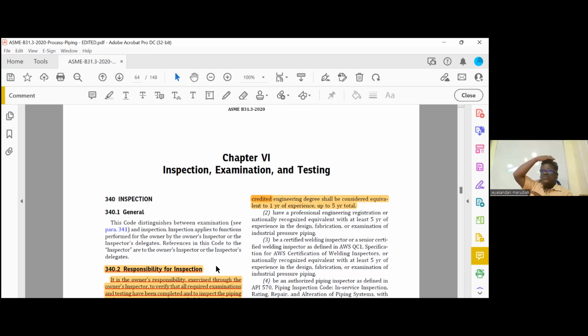Now you will ask a question. Suppose the welder is making only 5 feet. Then minimum length should be 6 inch. Spot radiography minimum length 6 inch. Closed book question. What should be the radiography requirement? Now, every 100 feet, 1 foot. Closed book question. Random radiography, every 20 joints, 1 joint.